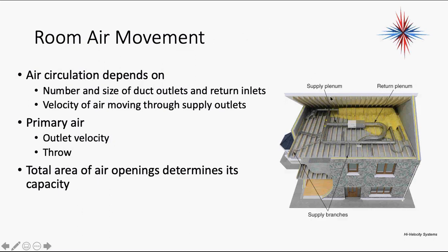And again, if we look at this opened up attic, we see an air handler in the center. We have a return plenum with a single return. By the way, we're going to talk more about that. That's a really bad idea. Okay, and then we have a supply plenum, and the supply duct and branches all come off this supply plenum. And again, we have a curved piece of flex duct in the front right corner of this. Again, we're going to talk more about that when we talk about proper duct design. There are a few really bad ideas in the system.